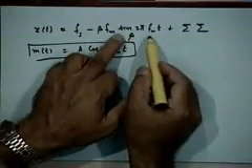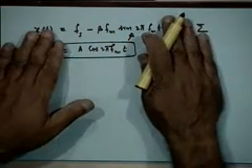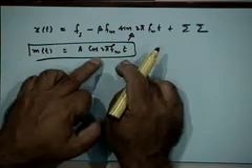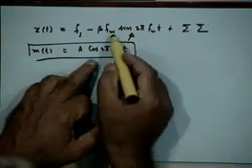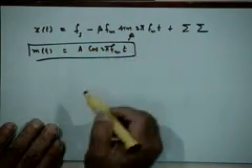The low pass filter essentially will give you a sin 2 pi f m t, isn't it? If you low pass filter it, you will get this term. To get cosine 2 pi f m t, you integrate it back. You integrate this, f m sin 2 pi f m t will become cos 2 pi f m t.